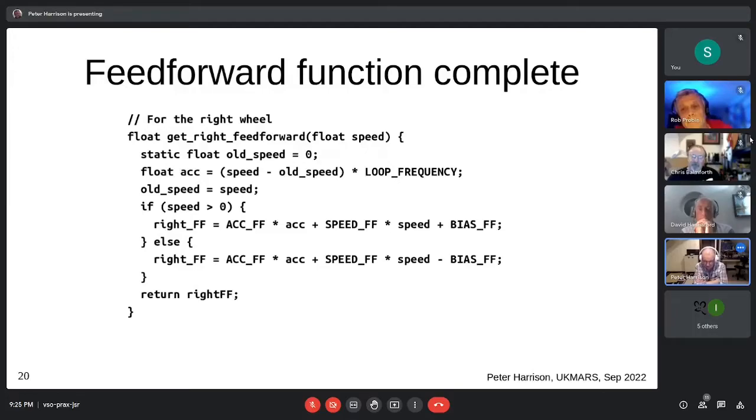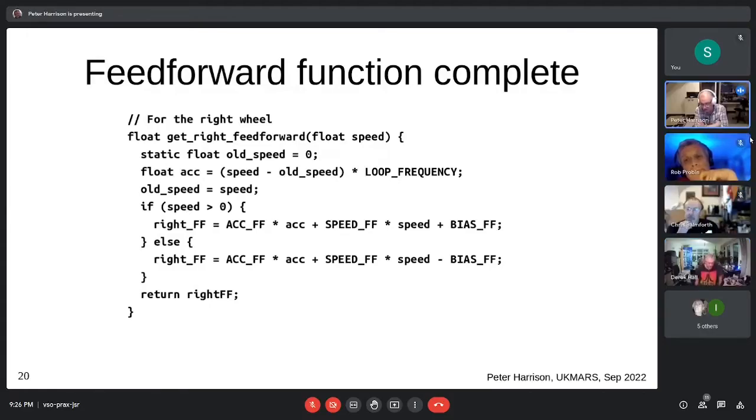Certainly, if you were on a line follower and plotting the course and recording it as segments with different curvatures, then a feed forward term based upon the anticipated rotational angular velocity during that turn would be a good thing. It would have the same benefits as it would for forward motion.